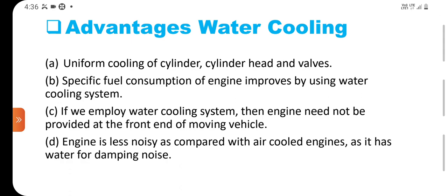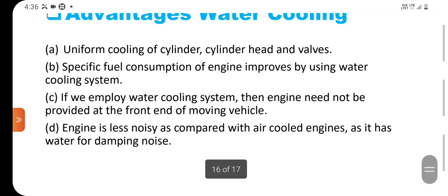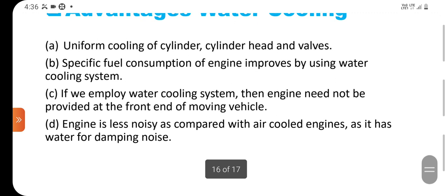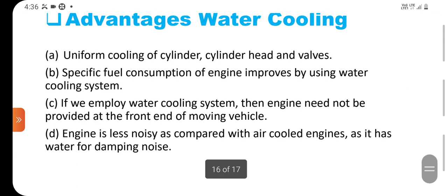Another advantage is that the specific fuel consumption of the engine improves with water cooling systems. Also, if we employ water cooling systems, the engine need not be provided at the front end of the moving vehicle.